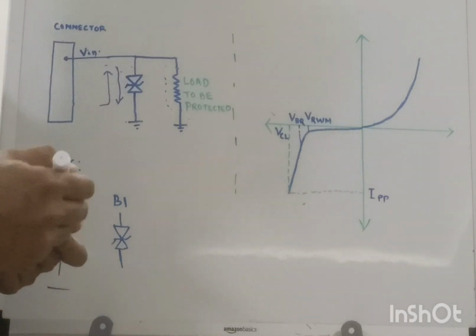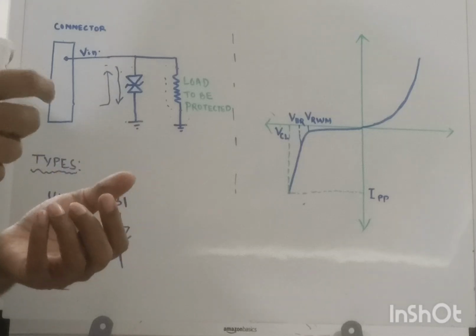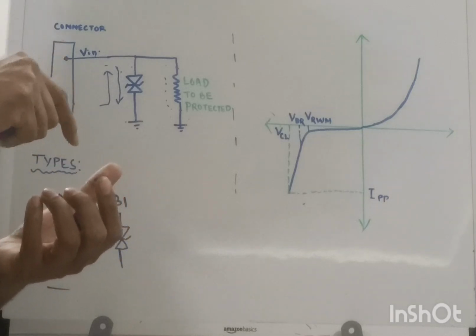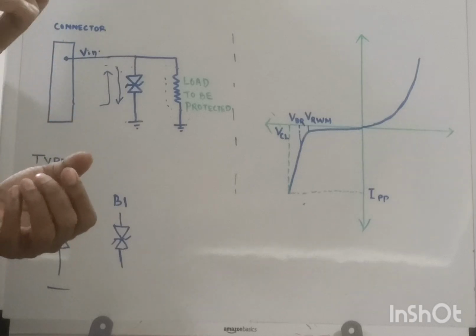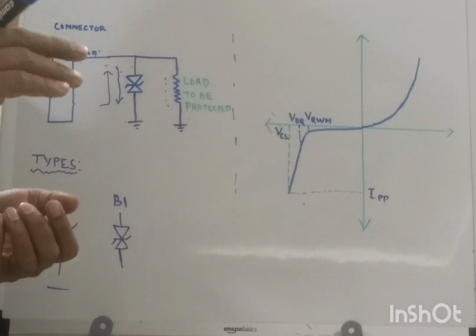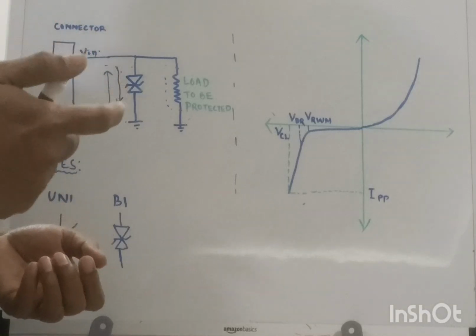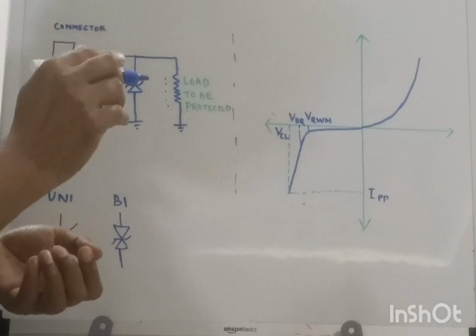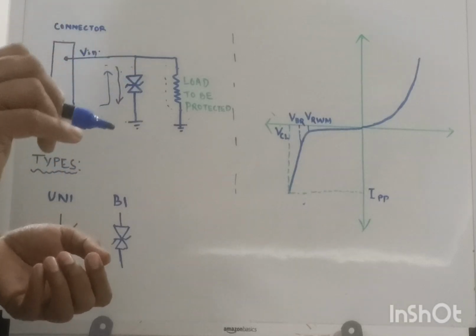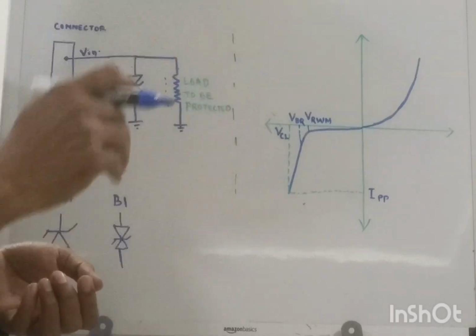That voltage usually appears through air, meaning your enclosure will be injected with ESD through air, or through the openings of your enclosure. Wherever you have connectors on your system, there you will have contact discharge. So you need to connect the TVS diode at those connectors where the signal of your board will come out or come in.